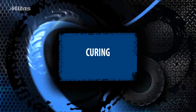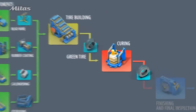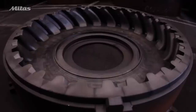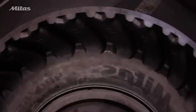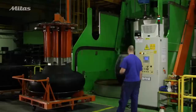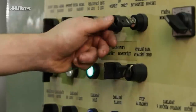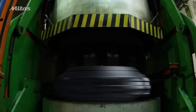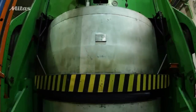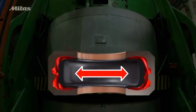Curing of the green tire. After tire building, green tires are cured in a process called vulcanization, in which the tire achieves its final shape and characteristics. This is a tire mold. Prior to curing, the green tire is covered with a solution that helps the green tire fill the mold. The green tire is placed in the curing press. The curing medium pushes the green tire into the mold.